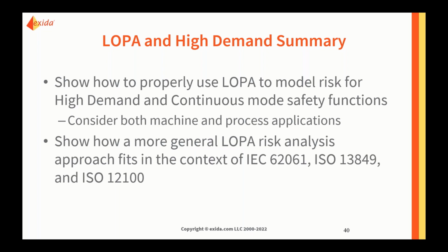Now, there's a separate question about hardware fault tolerance associated with high demand SIFs and low demand SIFs. Yes, there will be some slightly different requirements in the 62061 from the 61508 and the 61511 in all of this, whether you're following route 1H or route 2H, but that is somewhat outside the scope of today's presentation, and I would direct you toward a SIL verification presentation to clarify that.